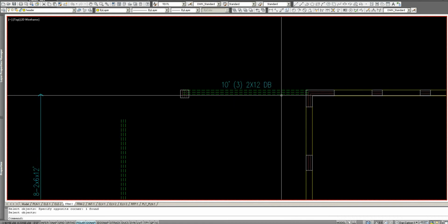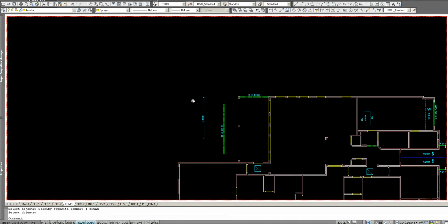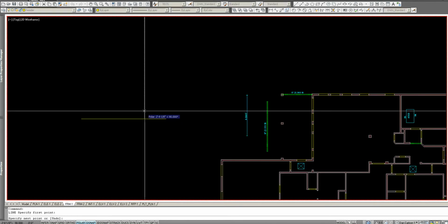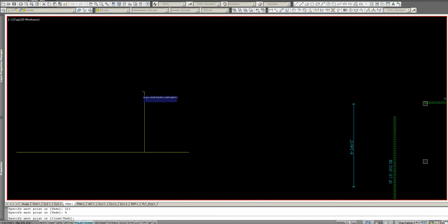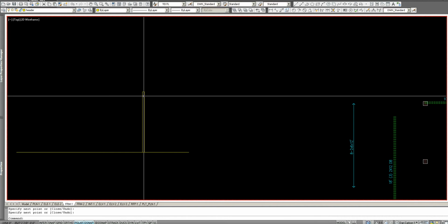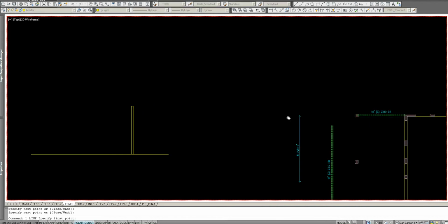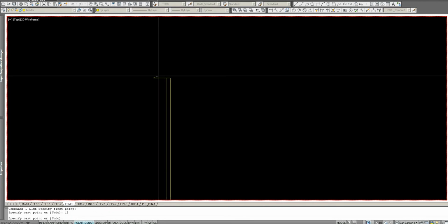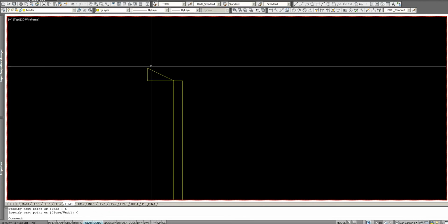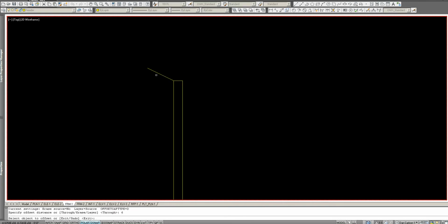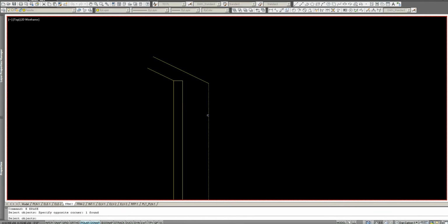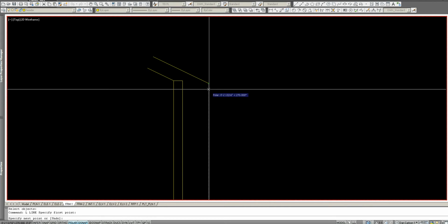And again, that's a dropped beam because I'll just show you real quick a cross section of that. If this is the wall of the house, and then the roof, and I'm talking about this wall here, okay? And we know it's, let's say it's a 7 and 12 pitch or 6 and 12 pitch. Offset this 6 inches, 12-inch overhang, and then come down 6 inches and over.